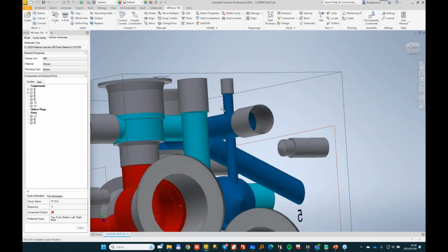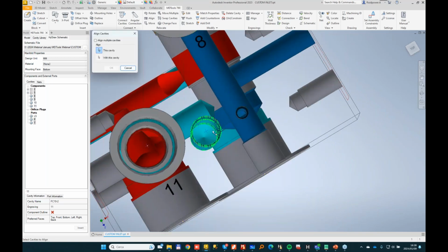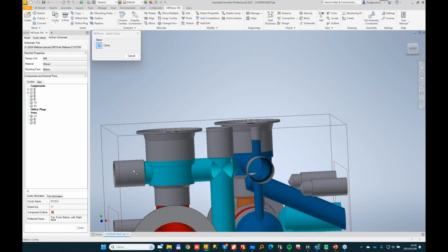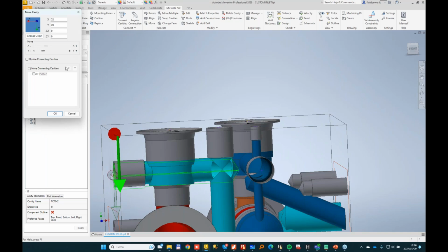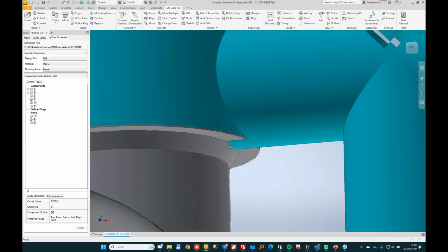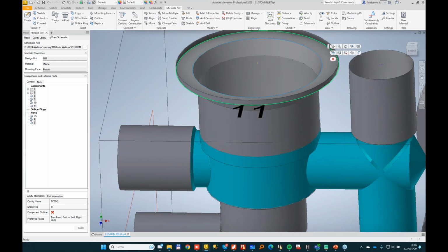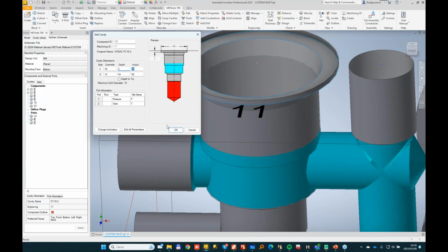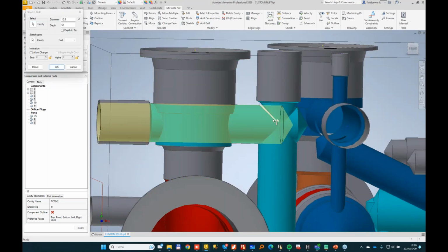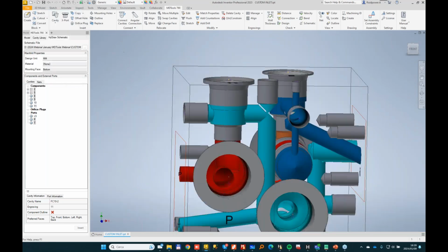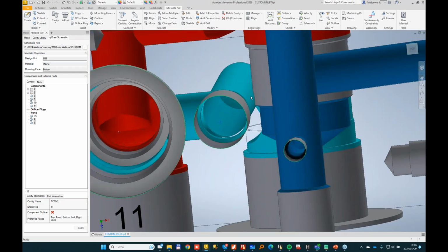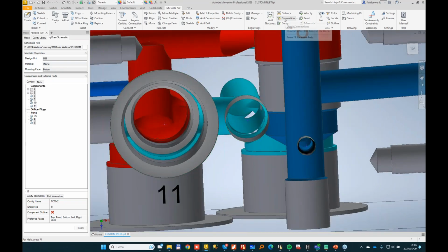So this is a case where you need to pay attention to the distance from the spot face. This is not bad at all, but I want to align these two cavities. Center to center is always better. I will just move my drill slightly down by 1 millimeter. In this case, I'm touching the chamfer, so let me edit the spot face depth. Let's make it 2 millimeter. And this is good. I want also to reduce the drill depth of my. Now, these drills are touching. This is a mistake. It will be highlighted by connection check.